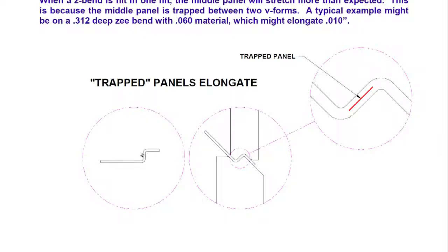So, if this were to be the top, there can be a bottom here. For example, a chassis can come here, this could be the top cover, and in the bottom chassis, if I pack the inside surface with a suitable elastomer which is probably stuck on one side, then I add a gasket grease and push it on top of it, I can make it splash proof.